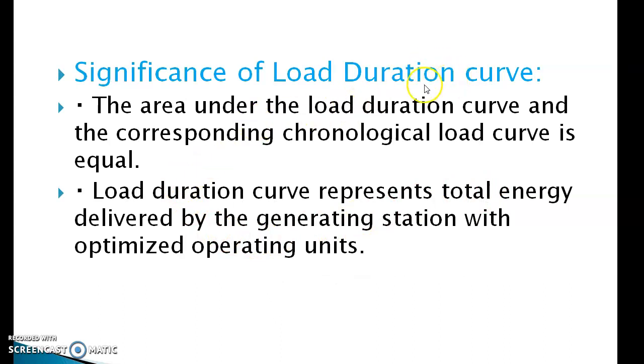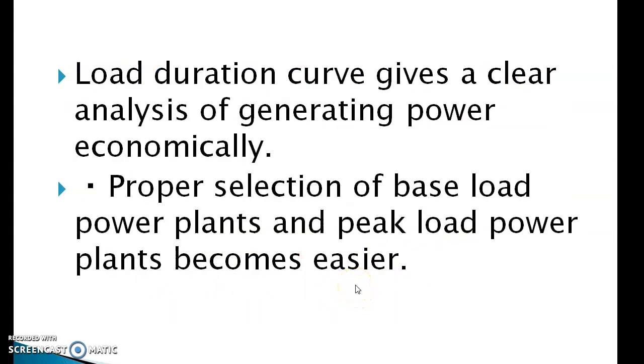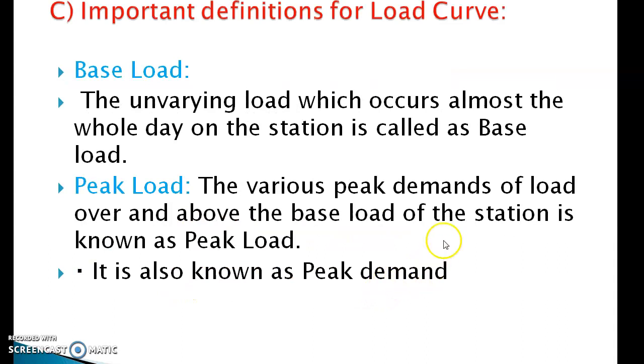Significance of load duration curve. The area under the load duration curve and the corresponding chronological load curve is equal. The load duration curve represents the total energy delivered by the generating station with optimized operating units. Load duration curve gives a clear analysis of generating power economically. Proper selection of base load power plants and peak load power plants becomes easier.